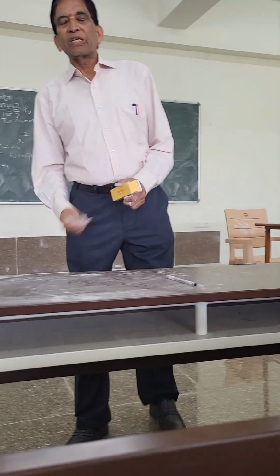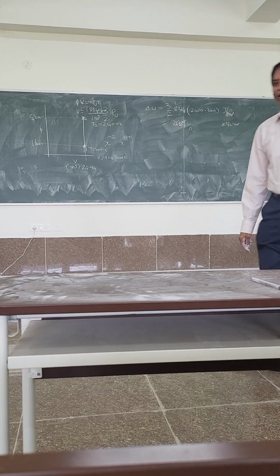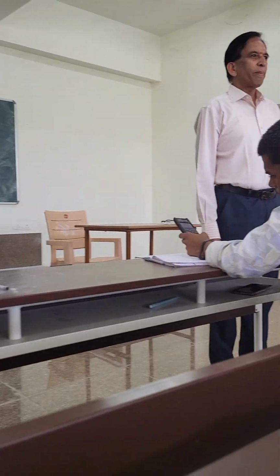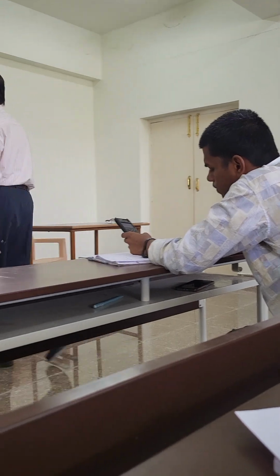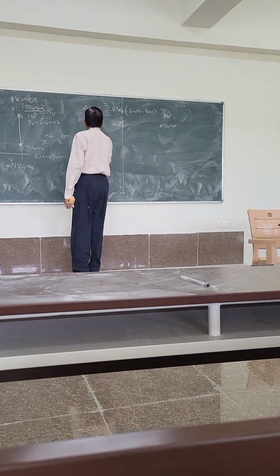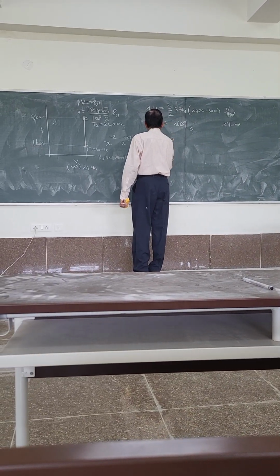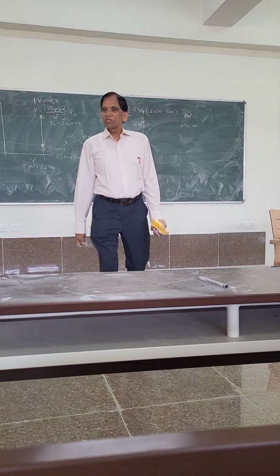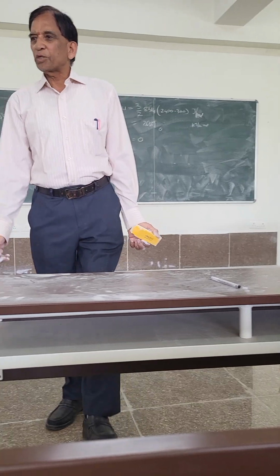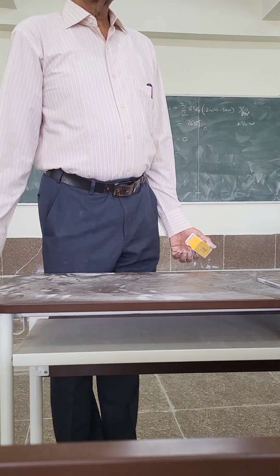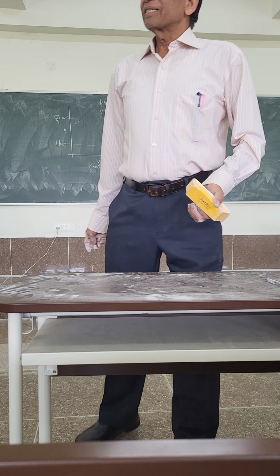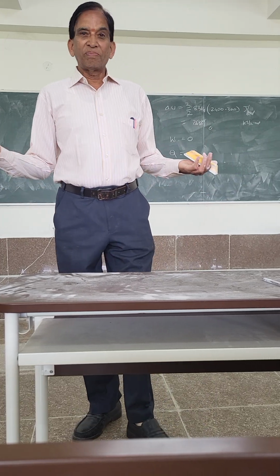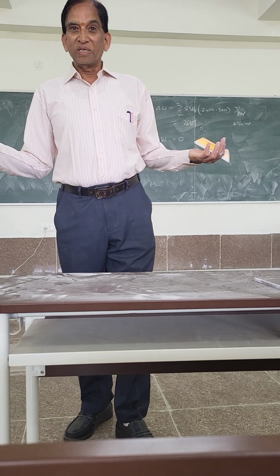Okay, that is the constant volume process. So if that is delta U, what is W done in the constant volume process? W is 0. Very good. Then what is the Q? Q plus W is equal to delta U. So for the constant volume process, Q is 26189, the same number. Okay, done? All of you are done? You have learned what is meant by a constant volume process. You know how to do it.